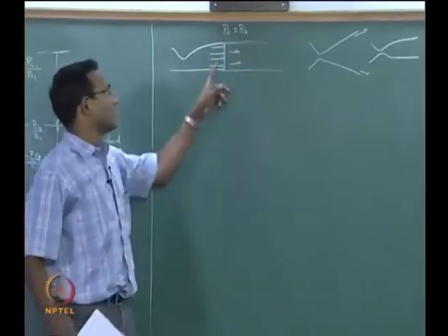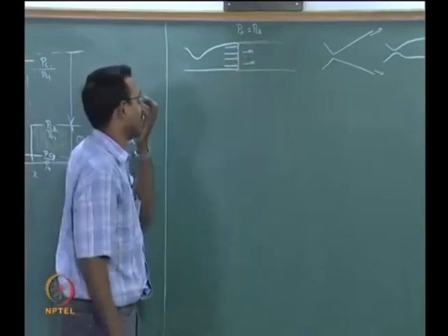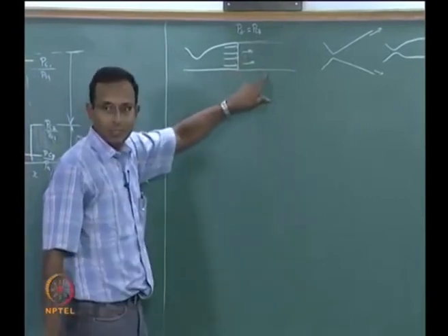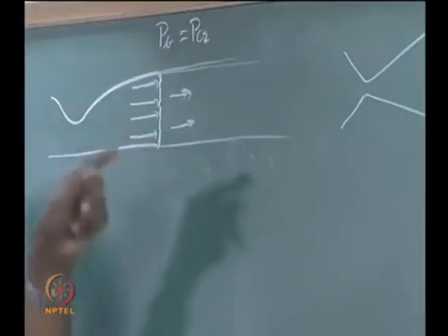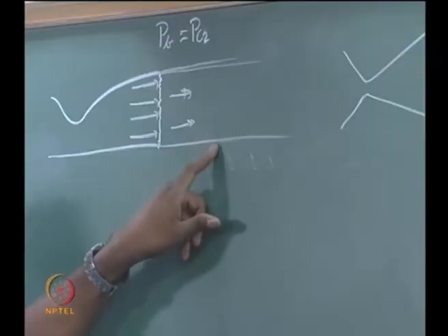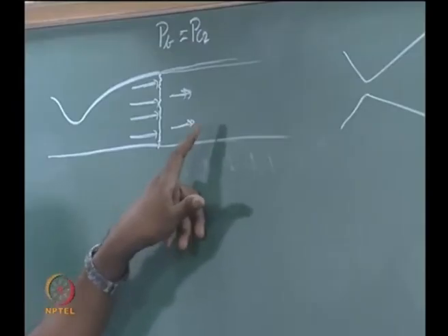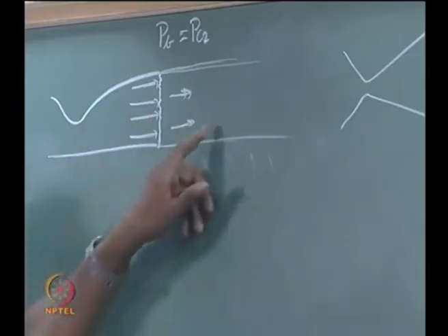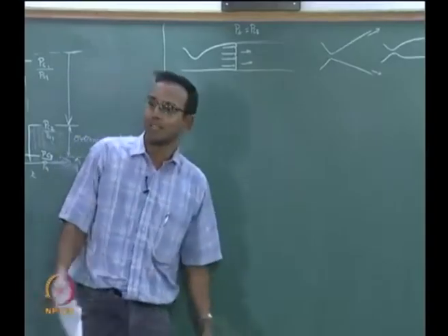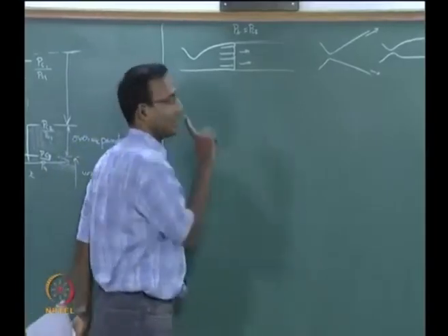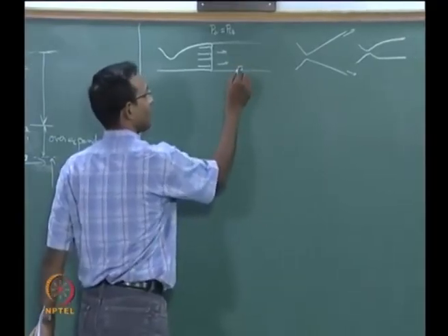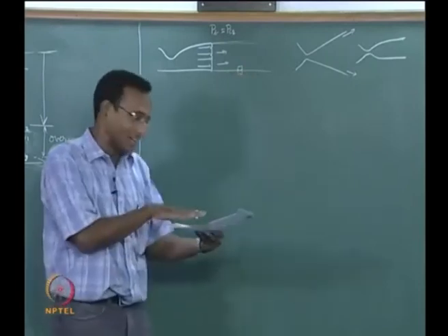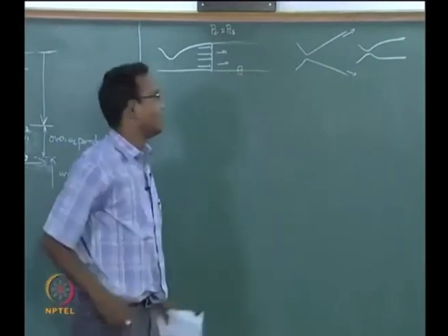We know high speed flow becomes low speed flow here, and the pressures are matching exactly. So, no fluid element is going to push the next fluid element, right? Pressures are equal across this line. So, this fluid element is happy that this pressure is the same as this, so no force is exerted, or both are equally applying force one against the other, and nobody is able to push against anybody. But we are neglecting the aspect that this fluid element is moving fast and the other fluid element is not moving, because of which there will be shear, which we are neglecting here.